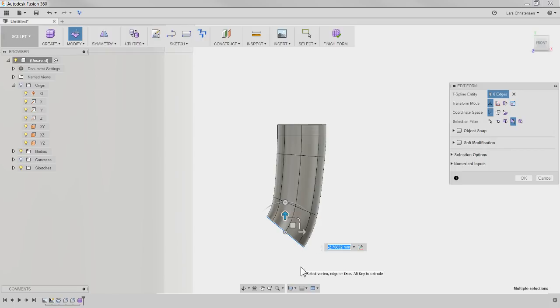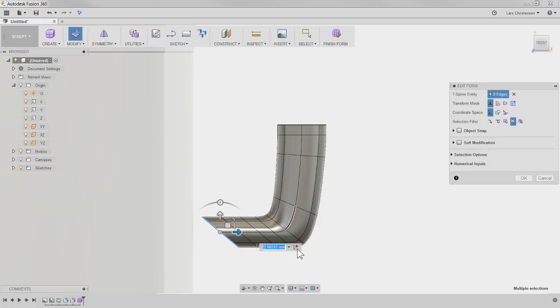Now another trick that you need to know, there's a lot of information here, another trick with that whole ring selected: if I press down Alt on my keyboard, and I start dragging one of these arrows, you will actually see I get a whole new segment. So let me just do that a couple of times. Holding down Alt and dragging, I'm creating new segments. You see that? So that's another neat little trick to know.